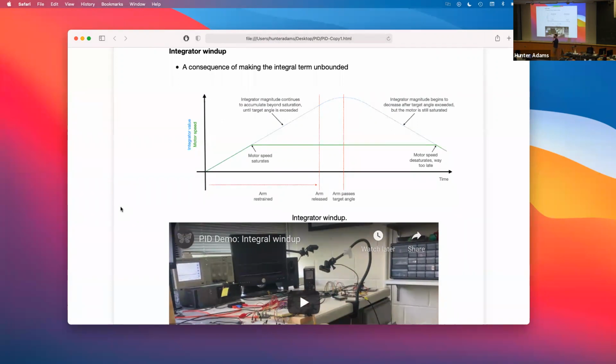That can lead to a situation where you turn the device on, you say go to 90 degrees, and suppose you just hold it down for a little bit. Then the error is going to stay large for a long time. The proportional part of the PID controller doesn't change, right? Because it's only ever looking at the instantaneous error. So from one time step to the next, the P part is the same. It's not growing. The I part, however, if you hold it down for a long time, the error initially at the first time step is large, and then if you keep holding it, it's large again and again and again. And it can just keep growing.